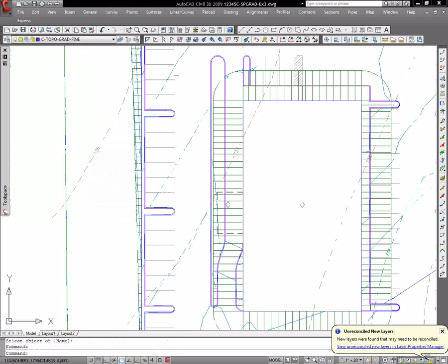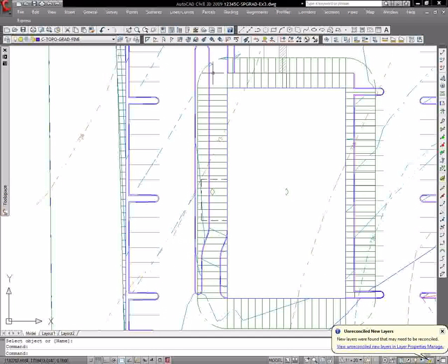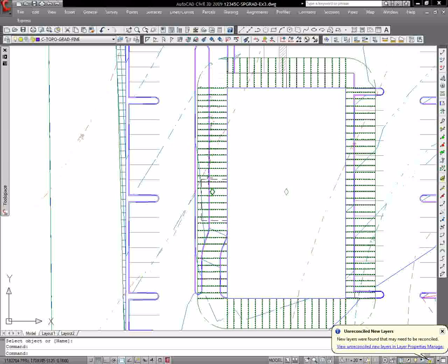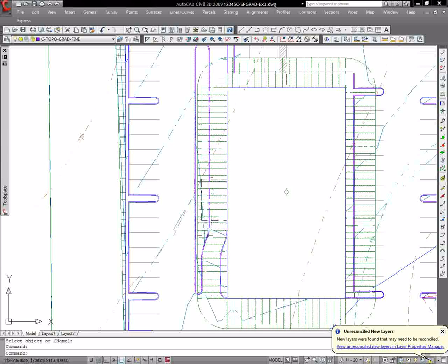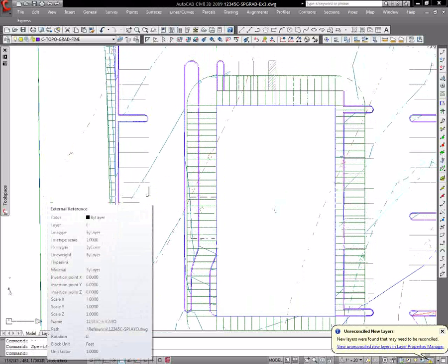And there you can see that nice constant grade. So in the parking lot area, we've got a nice constant grade of 1.46 along the curb. The drive-through, we're pretty much perfectly flat until about right here, and then we slope steeply down to the end of the driveway access. So that means right about in this location, this part of the curb is quite a bit higher than this part, and you can see that actually reflected in the contours within the island itself.